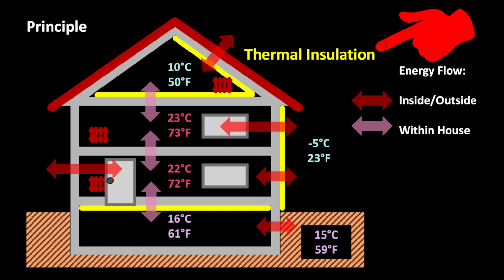But now comes the real difficulty, which is practically impossible to do without the support of a computer tool. In practice, it is usually the case that the attic and the basement, for example, are not heated. In order to calculate the heat fluxes that go through these rooms, we have to calculate the temperatures that we will get in these rooms after some time if we turn off the heating there. From our experience we know that without heating it is not quite as cold there as outside, because heat energy flows through the ceilings. However, calculating the actual temperature that will remain in a steady state is not an easy task.